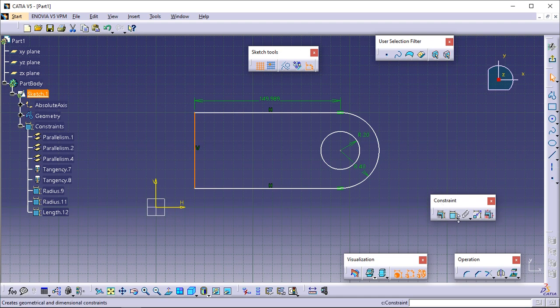Click Constraint from the Constraints toolbar. The geometry color is swapped to purple, which means that it is over constrained. You can use the sketch analysis to have a diagnosis of the over constrained elements. This option will be seen later on in this tutorial in the Analyzing Sketches section, which comes next. Click in the geometry to create the constraint.